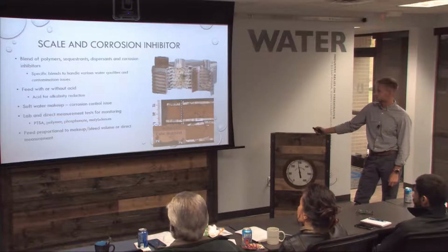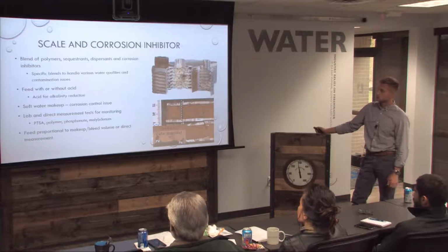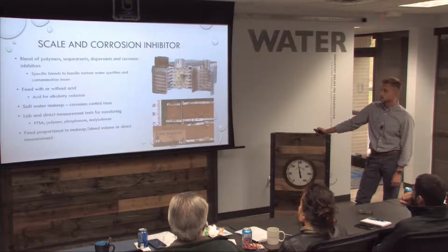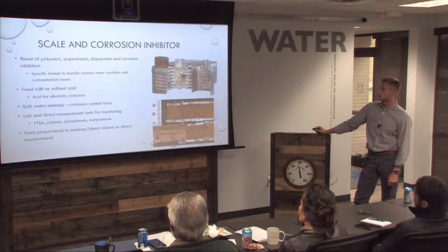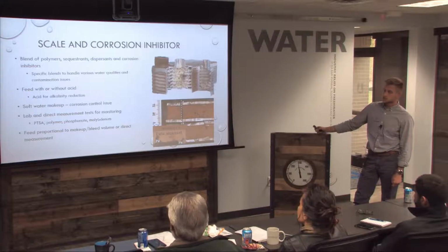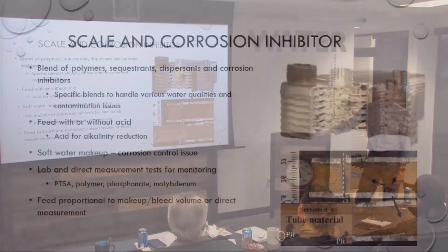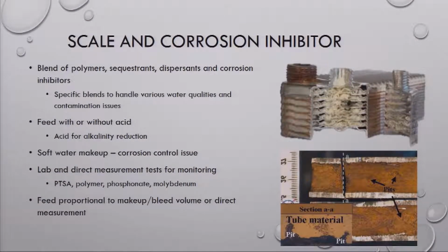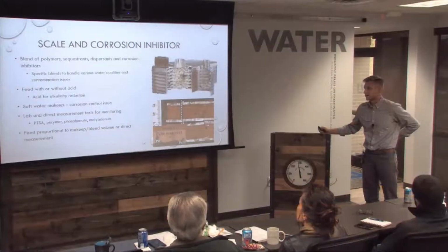So then there's ways to test for scaling corrosion inhibitors. So that's why you pay your water treatment people so much to come in and do some monitoring for you. You can do it remotely through the latest PTSA sensor. So on the other side, you'll see a panel if you want to take a look at the end of the day what a typical water treatment panel looks like. But that PTSA is a fluorescent tracer that we put in there. Not affected by temperature, it's not consumed by anything. So it really is the best way to test for your residual.